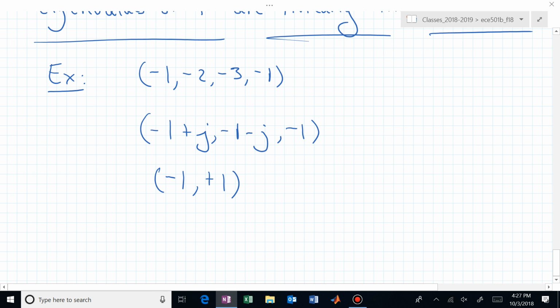I want to make sure that we all are seeing the same thing. The first set of eigenvalues, is that distinct or not distinct? Not distinct, because if you simply put down your complex plane and start putting x's on these locations, if you double up on your x's, then you have non-distinct eigenvalues.